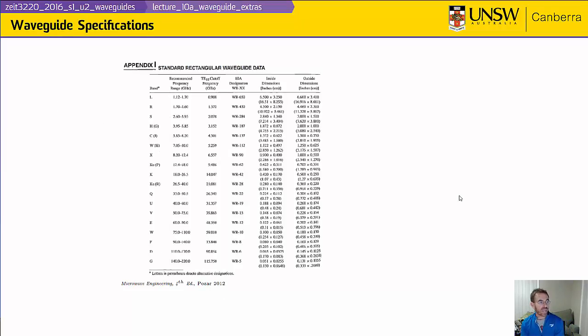So as Greg mentioned in class on Thursday, there are some waveguide standards. These are the waveguide standards and the associated bands of operation. The EIA designation, the WR-XX, which is shown here in this column, is giving the waveguide size, and the number stands for the dimensions of the waveguide in hundredths of an inch. And so WR90, which is here, has a waveguide size which is 0.90, so 90/100ths of an inch wide.